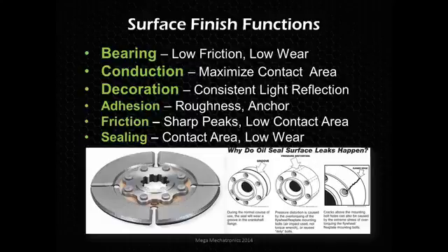You can see a groove worn into it, and that's pretty normal. You can actually repair that by getting a repair sleeve that you install over that with a slightly oversized rear main seal, and you can fix that up. I've done that before. And in the middle there's pressure distortion from improperly torquing the flex plate to the crankshaft